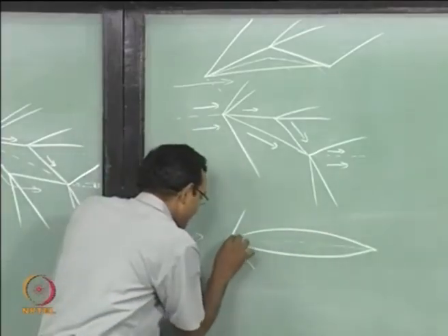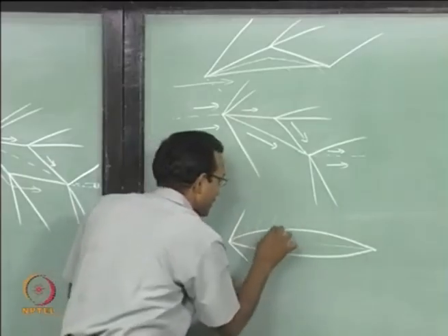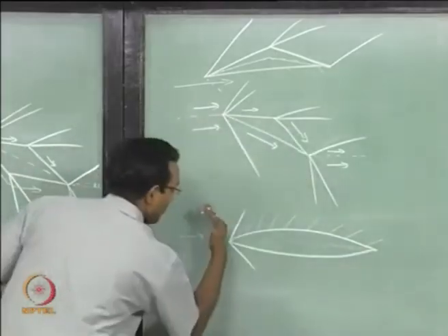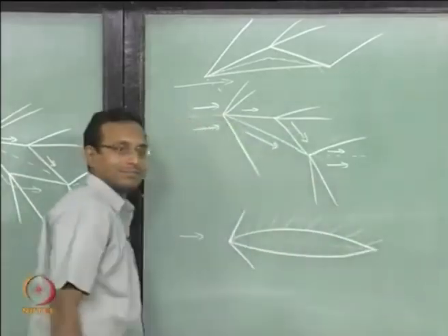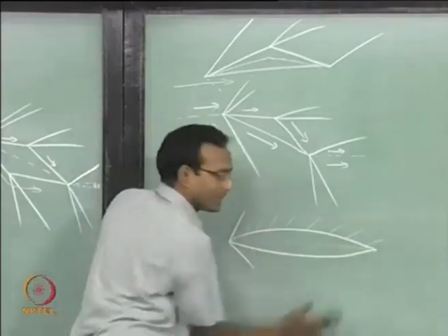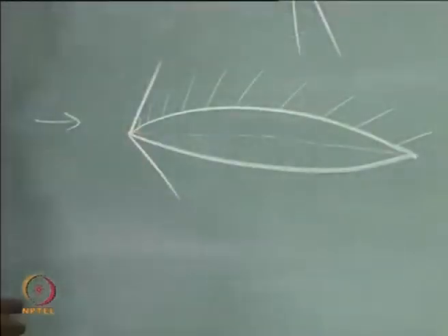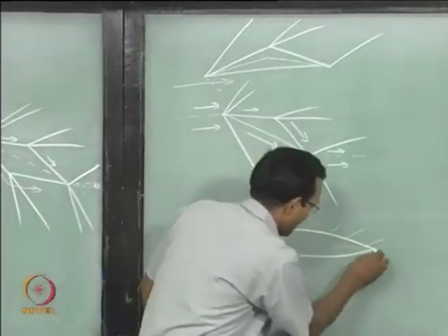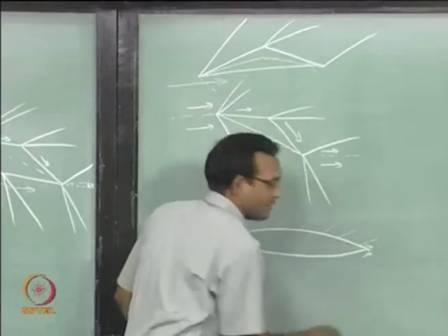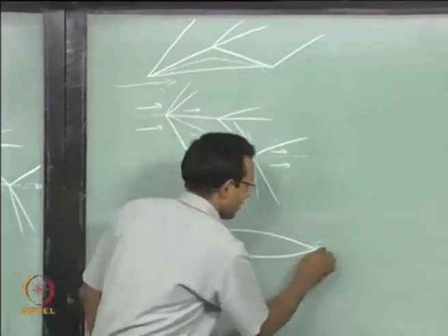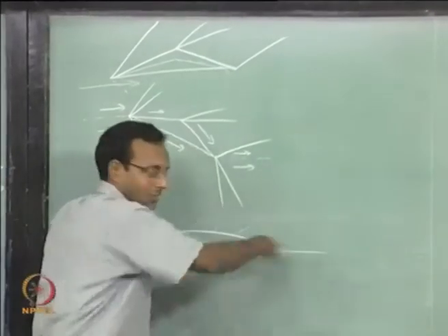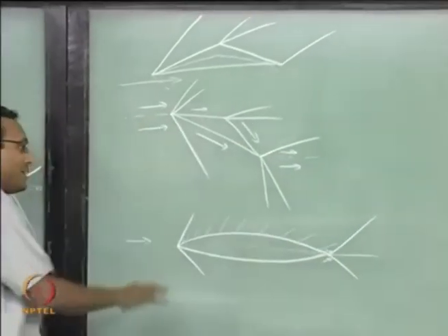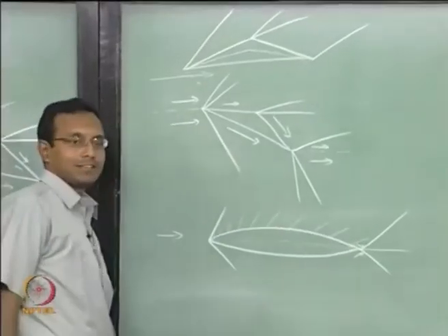So it is going to send expansion waves from here everywhere continuously, and if you notice, I am drawing very carefully, making sure that the slope of this line is going that way. Slope of this line is tilting that way. Expansion fan should be drawn that way. Now at the end, what will happen? The same kind of flow will come from this side. They will both interact with each other to go straight line at the bottom along the center, which means I have to have shocks at these points. This should be the case if I think about what the flow field looks like.